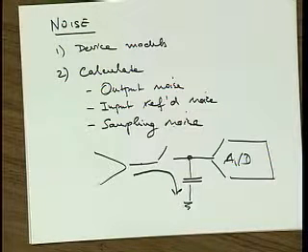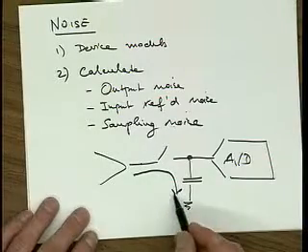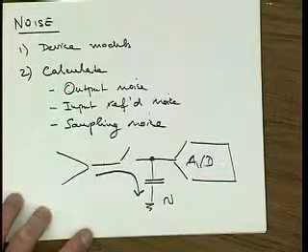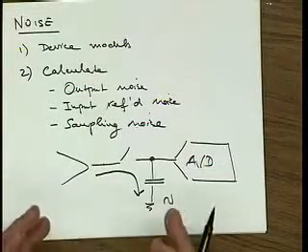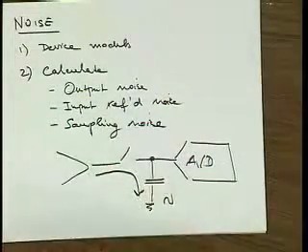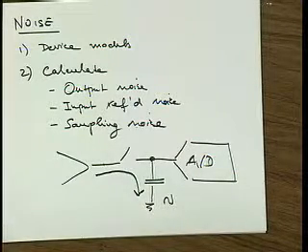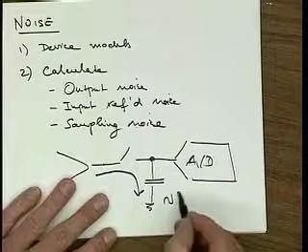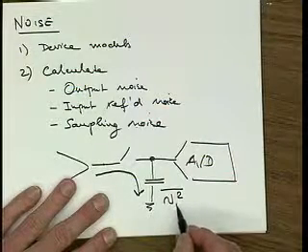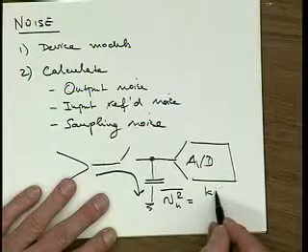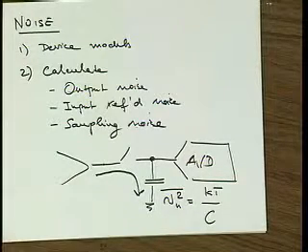And consequently, we somehow need to change our model on how to describe our noise. So the way we do that is we calculated the variance of the noise sample. Now, not as a function of frequency. What is the total variance of all these noise samples that we get there, right? Plus 3 microvolts, minus 7 microvolts, and so on and so forth. And we found that this was equal to kT over C.